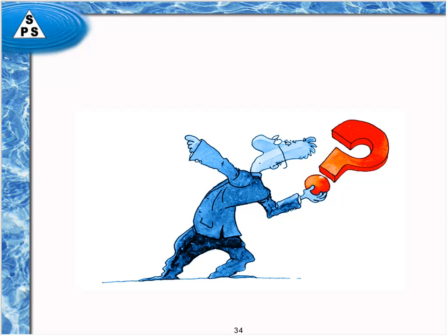The organisms that grow in a water system, and that is mostly the reason why these myths originate, is to somehow control or enumerate the organisms that are in a water system. It doesn't matter. The bugs don't know what the water is being used for. All the bugs know is that here's this pure water. It's a challenge to grow in it, but you select for those that can. And so it's actually irrelevant whether the water system is for medical devices or for sterile injectables. Bugs are going to try to grow, if they can, in a water system unless conditions are continuously hostile and keep them from doing so.